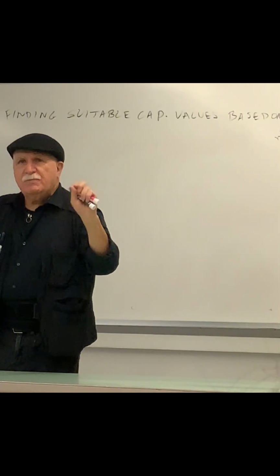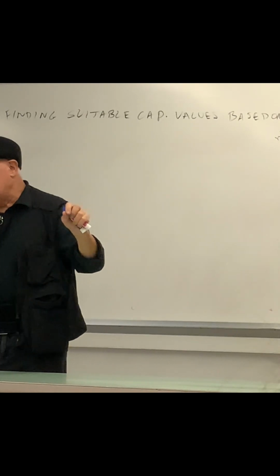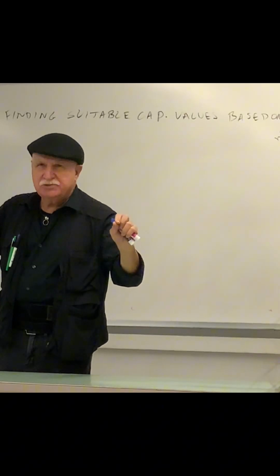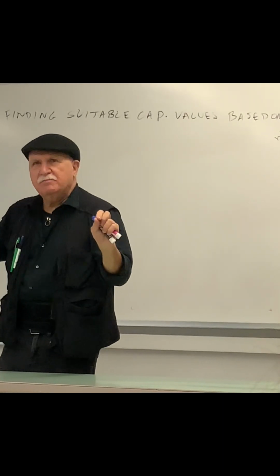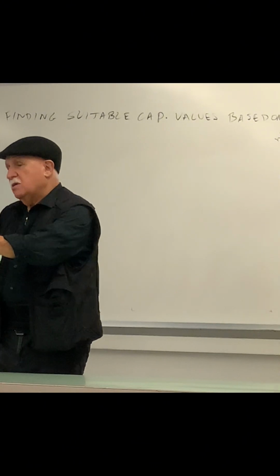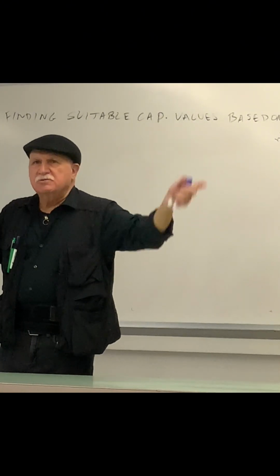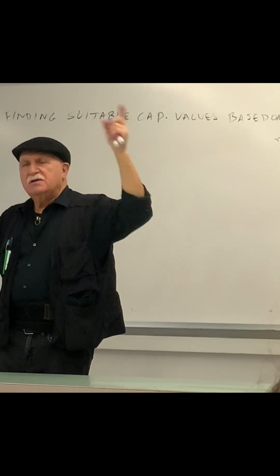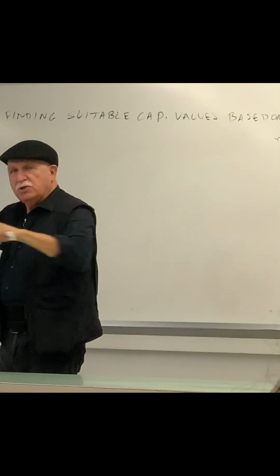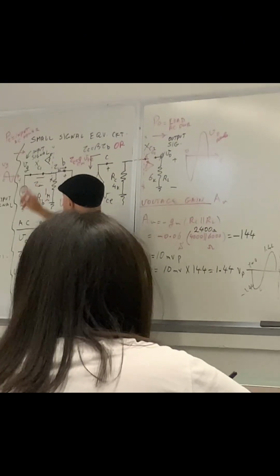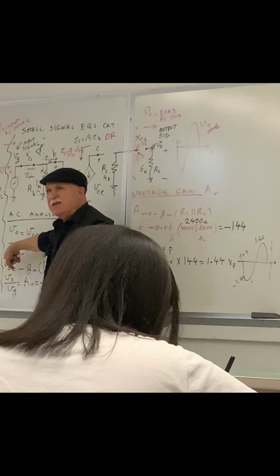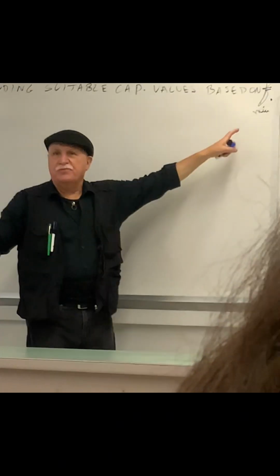For example, you're amplifying voice, the minimum frequency we will need to have amplification at is about 80 hertz usually, maybe 60 hertz. That's the minimum for a good bass. And then all the way up to what you can hear, 20 kilohertz. You can't hear 100 kilohertz, but something like 19, 20 kilohertz. So you want this to be considered as short. Don't care about the 20 kilohertz. Just take care of the low end of the frequency, this guy, F minimum.